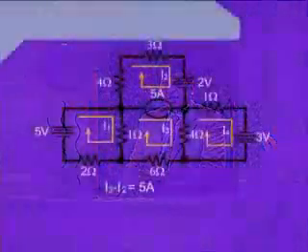The problem is arising between mesh number 2 and mesh number 3, because we don't know the voltage drop across the independent current source. Let's assign an unknown voltage Vx, which is observed across this independent current source. Let us see this on the slide.